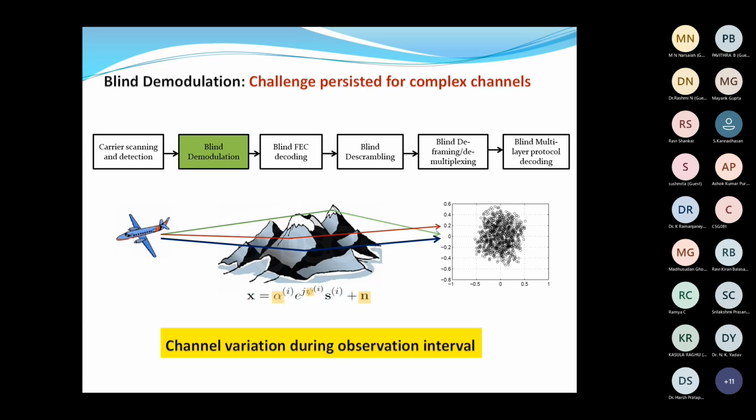The conventional equalization approach that comes to mind in a conventional communication system applies measures like LMS-based equalizers, which employ a pilot sequence, and other methods like decision-directed approaches. However, as we have seen, we are completely blind and don't have any parameters. Even the modulation scheme is unknown. So in this scenario, we need a completely different set of approaches. Let us get into how we mitigate this and how we formulate the solution for a blind scenario.